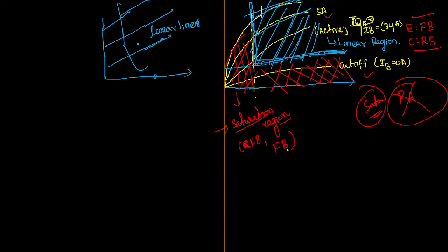It's a really amazing device, because if both diodes are in forward bias we would think, it is good sir, both are forward, we can operate it in the active zone. But you forget to remember one more thing: the diodes are in back to back connection. They are not connected like this. If they were connected in this way, then it would be very good to observe both in forward bias. See, both are in opposite direction. One will be like this, another one will be like this.